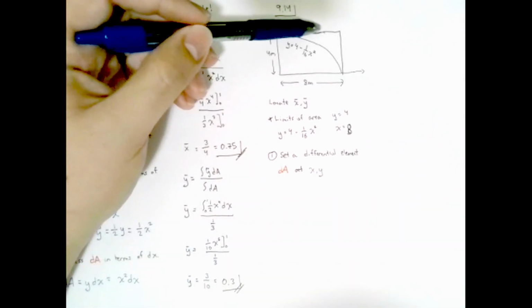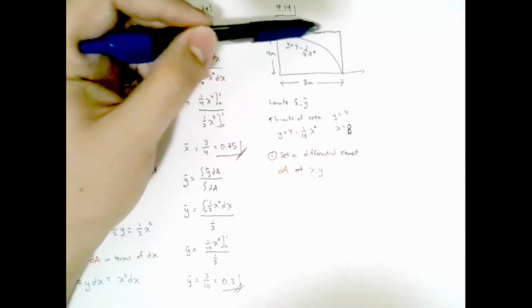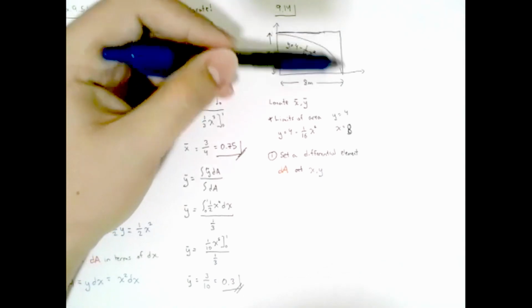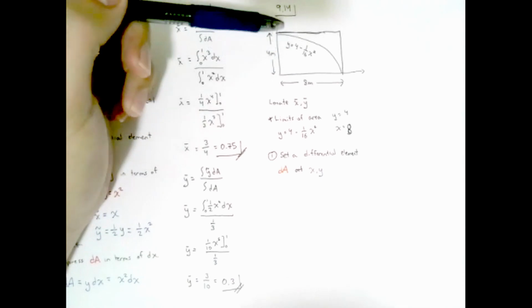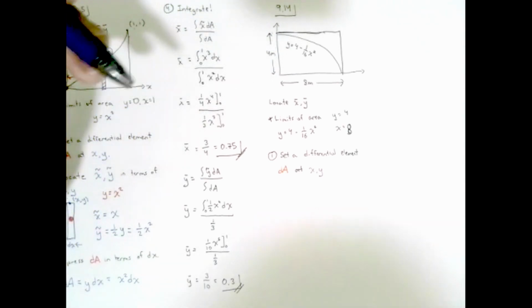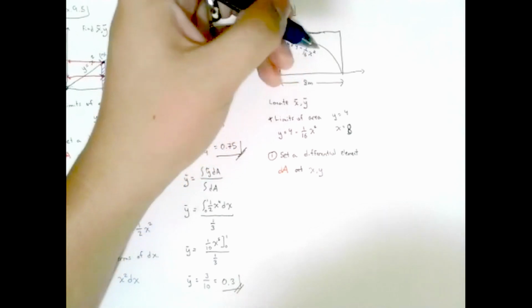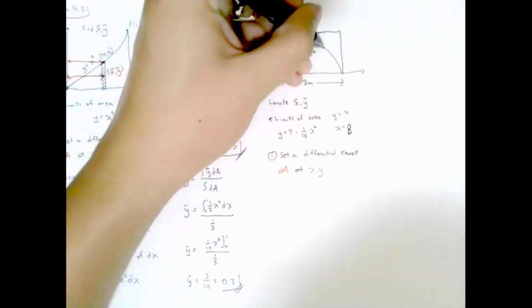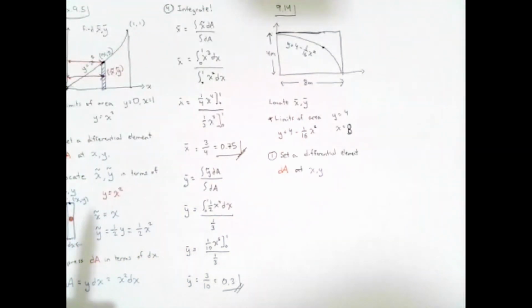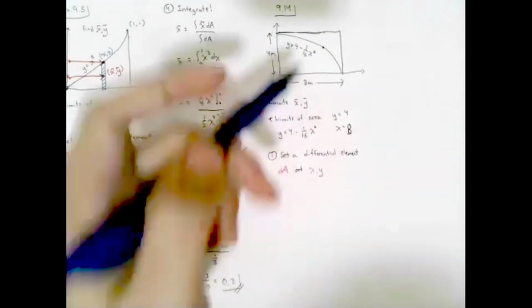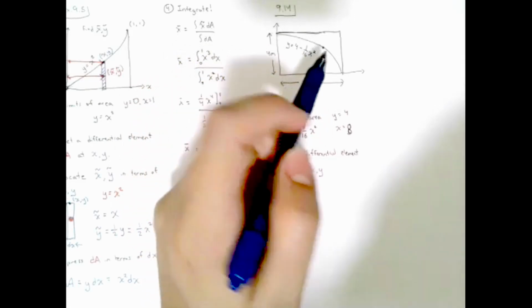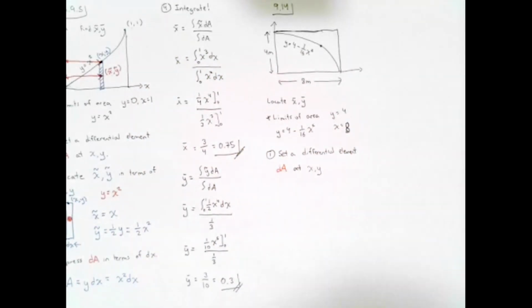My issue with bounding or locating my x, y in this curve is that if I integrate over a straight line, I just get the area of a rectangle, and I don't want that. Therefore, I'm going to make a judgment call and say that my x, y should most likely be located still on this curve. And you'll notice that when we find our x squiggly and y squiggly, that is going to make up for any differences between this shape and this shape. So we'll see them in just a second. So let's just go over this problem step by step.